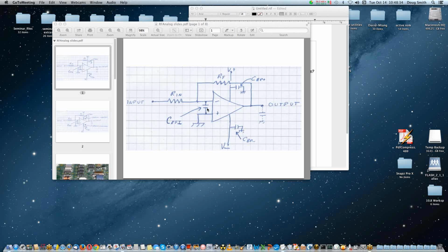As I mentioned before, you could slide a copper board sheet between them, and it would just make the thing go quiet, even though it was ungrounded, because the local fields of the digital circuit were small enough that all the currents were contained within that shield, and that's for fields that are physically much smaller than the shield. You don't need to ground the shield to get shielding, but of course that was totally impractical. Our system people didn't want to hear of putting copper plates in between the boards, so we ended up with little capacitors there on the input of the op amp.